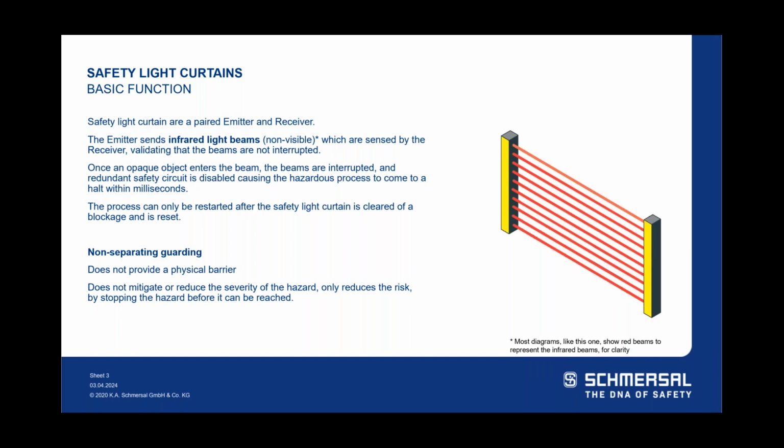Once an opaque object enters, the beams are interrupted, and our redundant safety circuit is disabled, causing the hazardous process to come to a halt within milliseconds, which is really important. We'll talk further here about safe distances when we start and the need for calculations when we're installing these light curtains and how to install them properly.